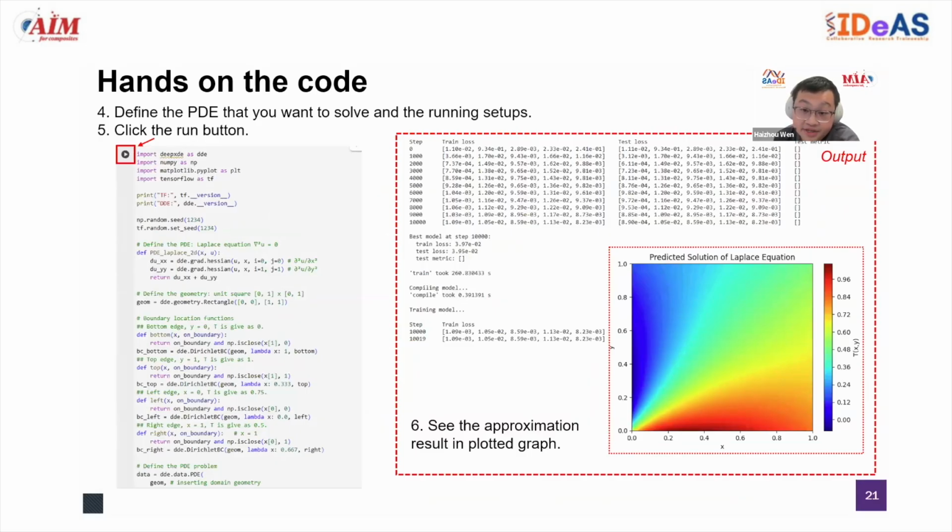Then we just keep the preset parameters and run the code. We would have the outcome. You would see a resultant graph showing the steady temperature field in the square domain. Since our setup values for temperature on the 4 BCs are evenly spaced, we can see the color distribution is symmetric along the diagonal line.